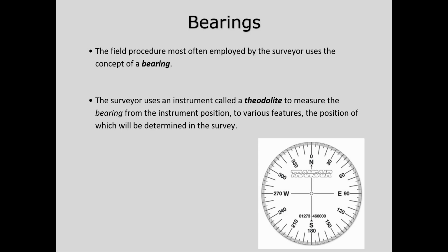So it's great to say the road is 1 kilometer long, but we need to know in what direction that 1 kilometer length goes. Now the bearing concept uses north as a starting point, and from north we start measuring a bearing angle, what we call clockwise. So if you can see, there's a line here. For example, if I draw a line, let's say this is the starting point. It's always going to start from here. It's always the center of the coordinates here, our starting point.